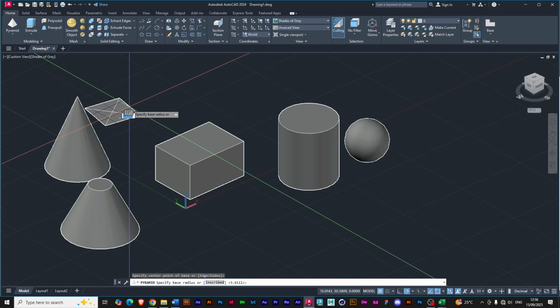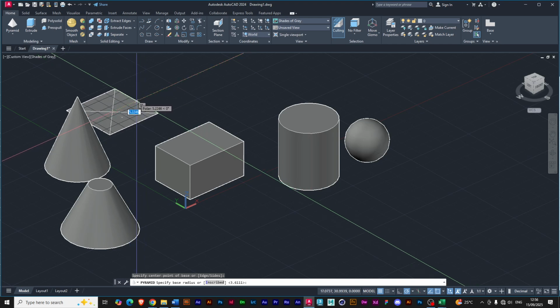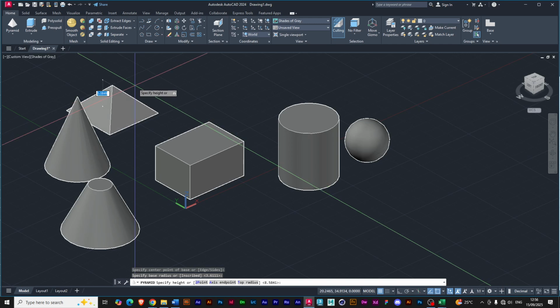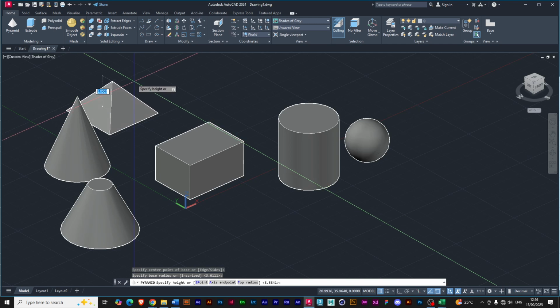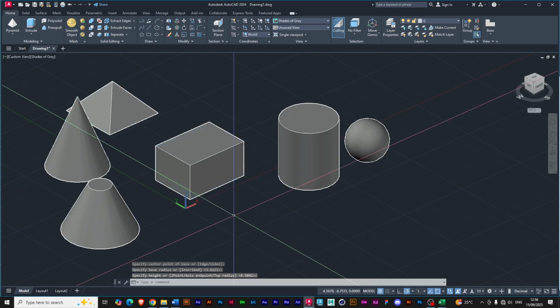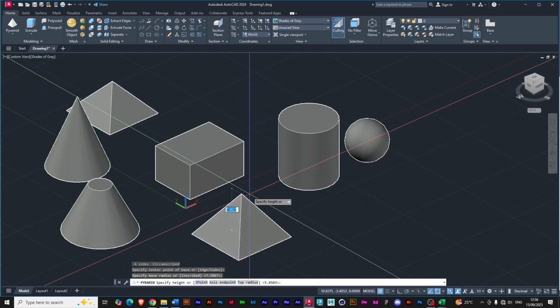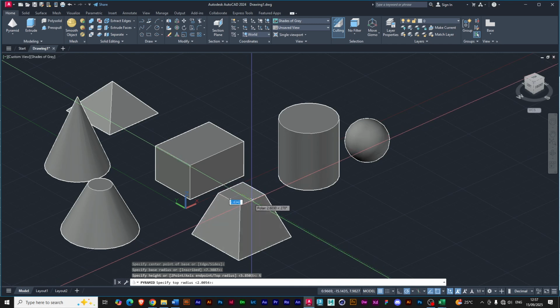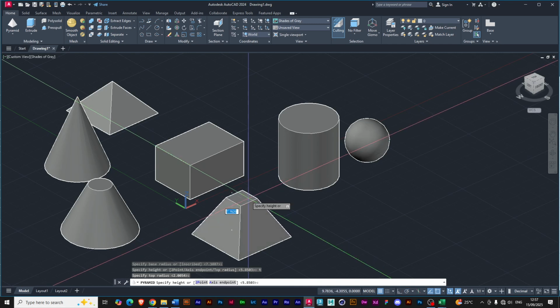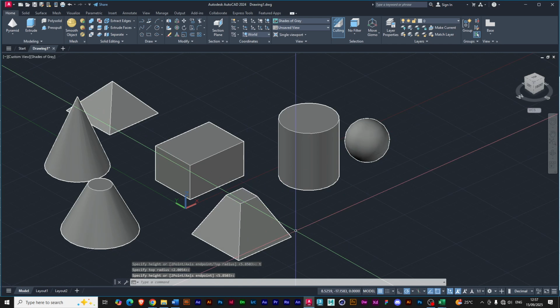So right now, we'll just draw this box and draw up, and then you can still do that same thing with top radius. If you don't want to make a sharp edge, you can click on T and now make it have a flat top instead of a sharp top. So let me draw this one first. Then do the same thing. And while I'm dragging, press T to give it a sharp top so that I can have that wedge kind of feel.